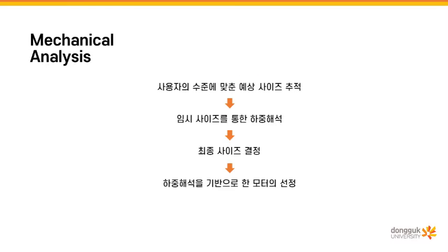First, we estimate the appropriate expected size according to the user. Next, we conducted load analysis through this temporary size and decided the final size, and finally we selected the motor based on the load analysis.